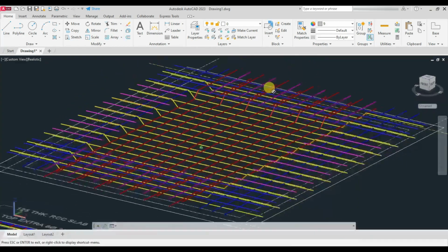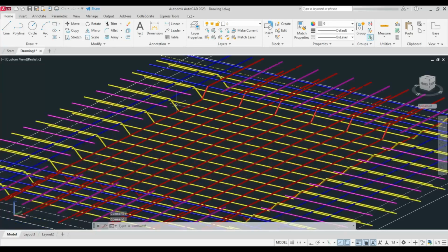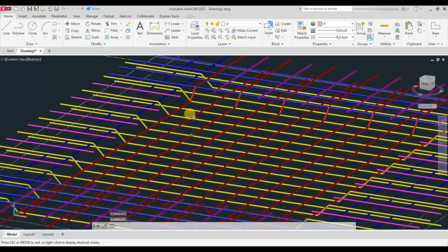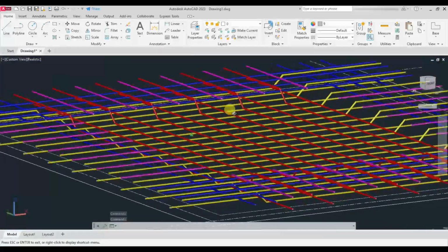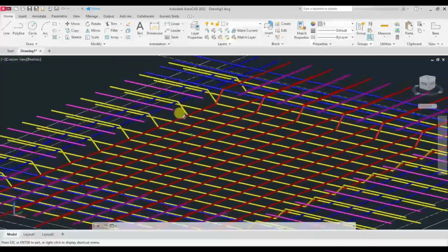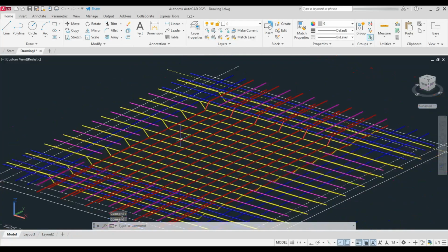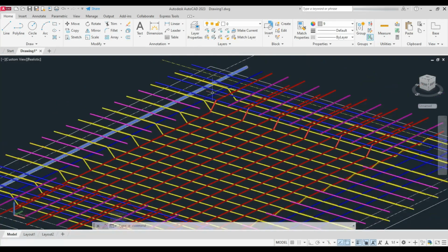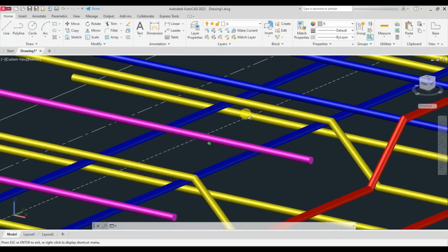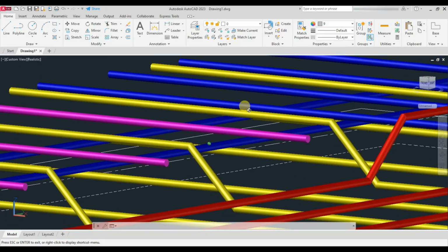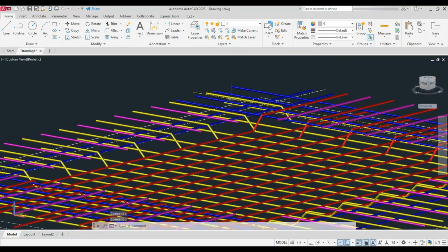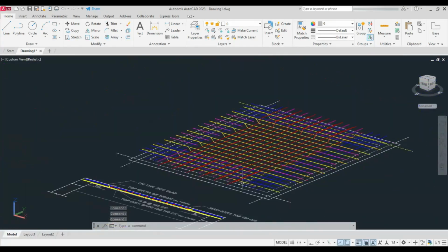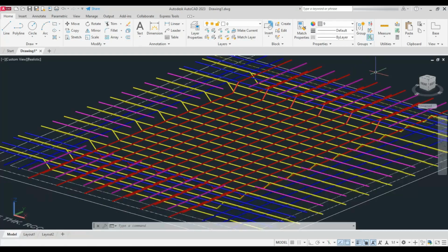After laying main bars in both directions, distribution bars are provided on all the four sides to provide support to the main bars. After the crank portion, a moment will develop at the upper portions on all the four sides. So to counter that, the top distribution steel is provided and it is laid below the main bent up bars, represented in blue. Next is the top extra bars of 8 mm and the center to center distance is